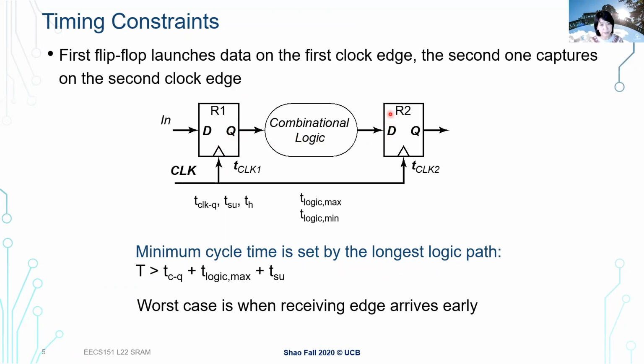So in this particular case, if we think about the critical time here, or where the longest path exists, when we think about the propagation delay, as a rising edge clock, at the beginning of a new clock cycle, we first need to go through this clock to Q delay to make sure our Q output is properly set by the input. So that's the first part, the clock to Q delay, as we specified here. And once Q is set correctly, that's basically the delay to go through the combinational logic.